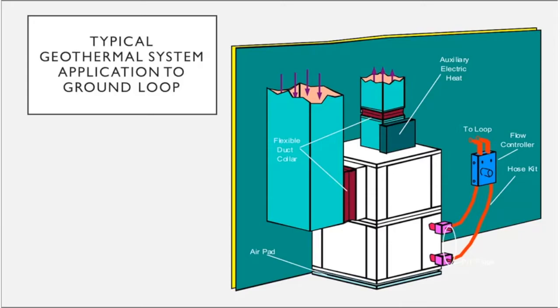The typical application nowadays that we sell the most of is forced air, where we have what we call a package unit that does both our heating and our cooling, with the heat pump section on the bottom and the top part being your air handling section. From an efficiency perspective, we have a very, very small space for the refrigerant to travel through when they're packaged together. So package units are a very easy system to install and have very good performance.